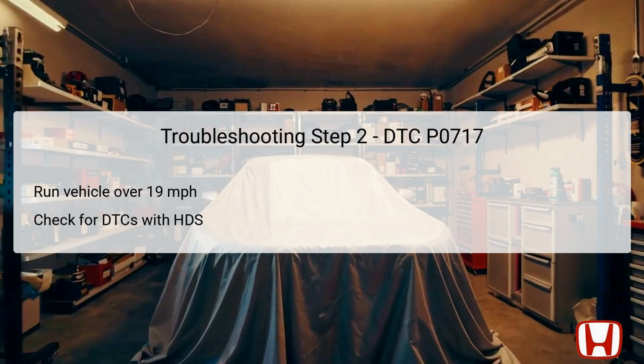After this period, it's important to slow down and stop, so the HDS can be used to check for any pending or confirmed DTCs. If the DTC P0717 appears again, it confirms that the failure is not transient and requires further investigation. Conversely, if the code does not reappear, it may indicate an intermittent issue or a temporary glitch, warranting checks for poor connections and loose terminals between the torque converter turbine speed sensor and the TCM.